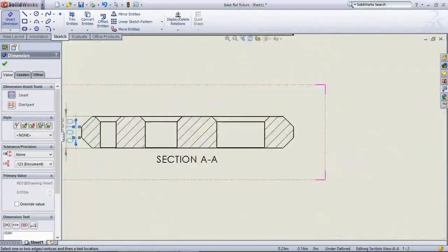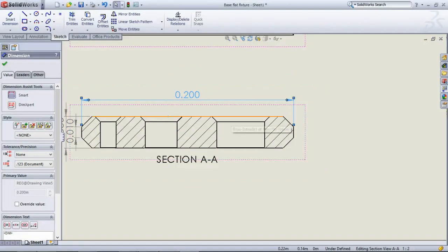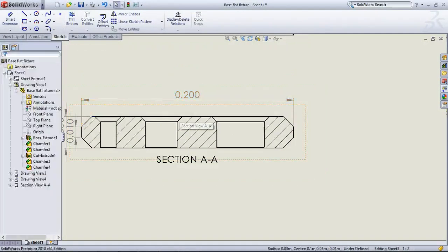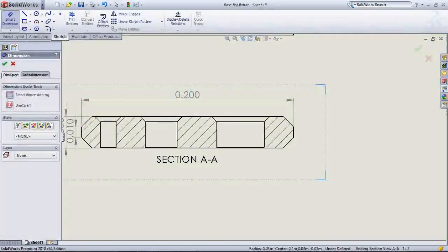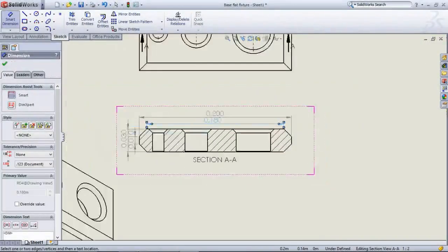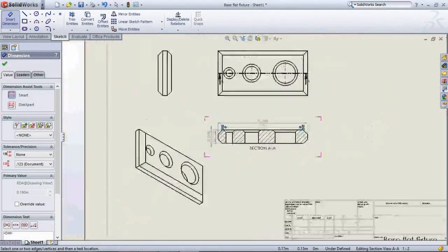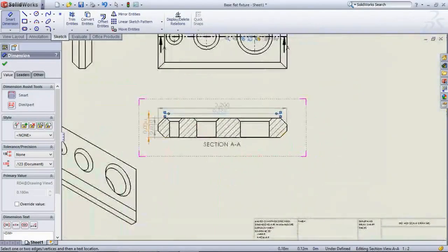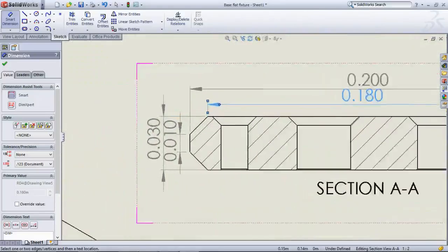Here the unit mentioned is meter, the MKS system, which means meter, kilogram and second. I'm just going to choose the MMGS system, which means millimeter, gram, second. So no problem. Just project all these dimensions here, and once we finally choose the unit, all the further units will be changed automatically. So just click the points that you require.